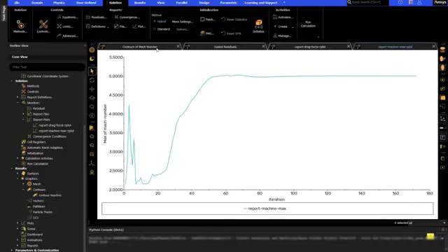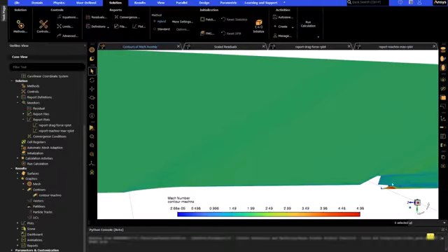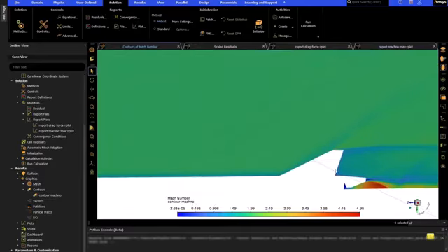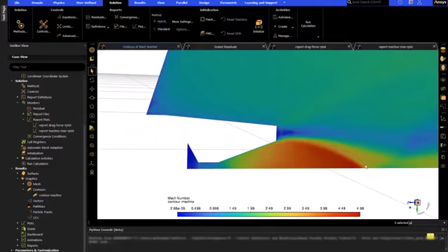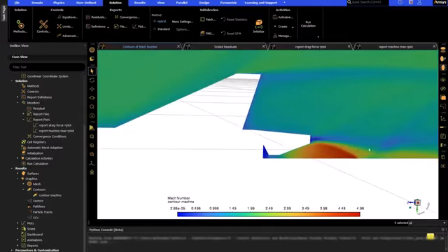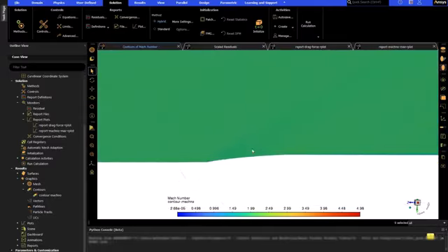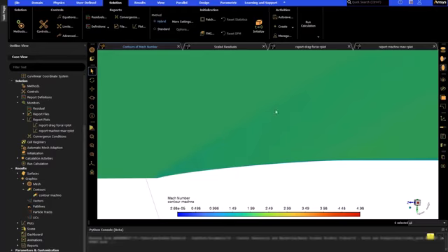Returning back to our original converged solution, we can visualize the solution by inspecting the contour plane that we created before. The contours of Mach number show the velocity variations in the flow field, with abrupt changes in the constant Mach 2 flow field and jet exhaust representing shock structures. A shock can also be seen coming off the nose of the rocket.